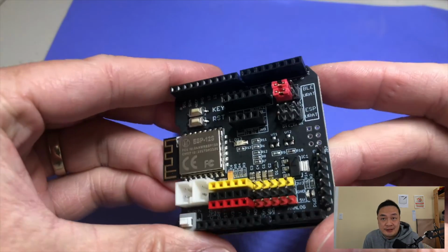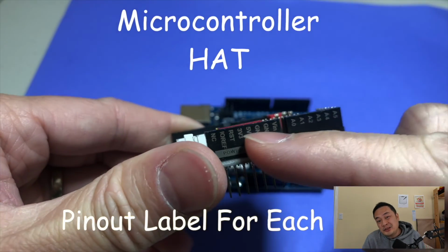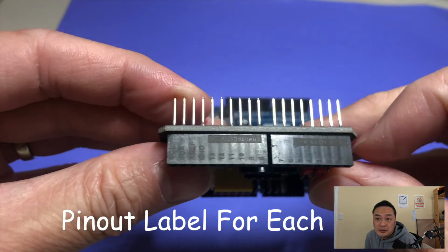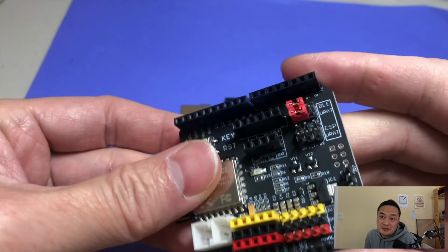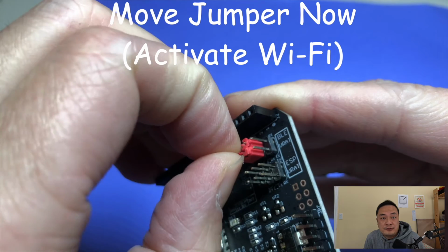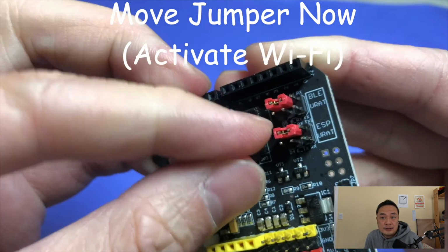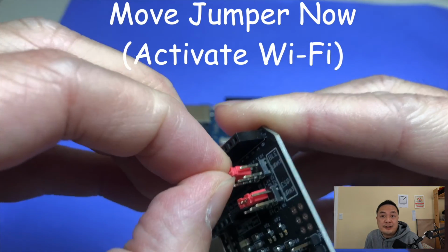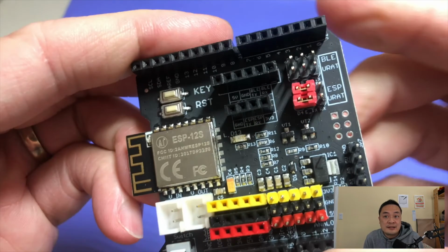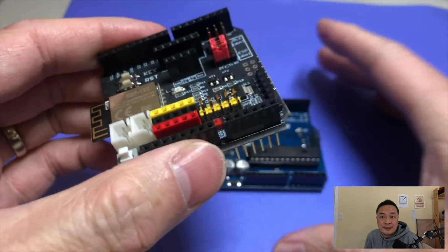And this is another type of controller. I call it a hat. Technically, you call it a shield. Notice the printout label corresponding to each hole. You're going to work with those pin holes a lot. So we're going to activate the Wi-Fi feature first. You just move the red jumper to the Wi-Fi area of the printout. I'm going to pause the video so you can see clearly where the printout is located, right?